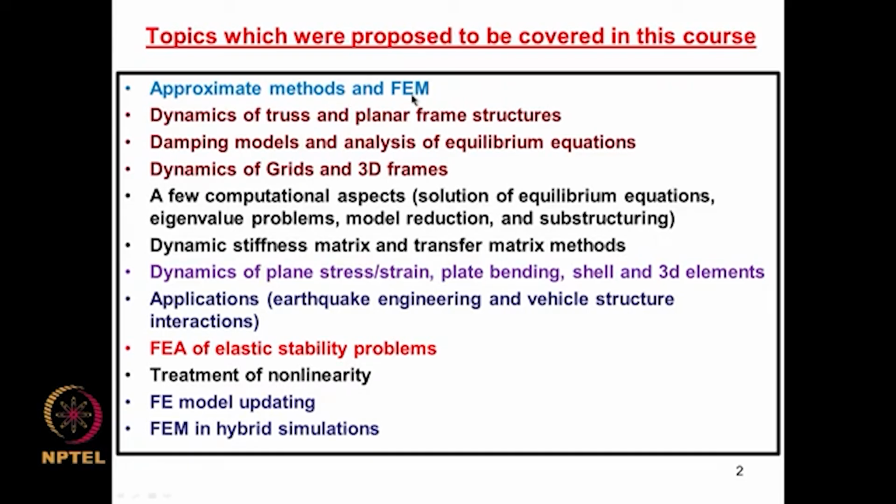The approximate methods and finite element method, dynamics of truss and planar frames, damping models and analysis of equilibrium equations, dynamics of grids and 3D frames, and some computational aspects like solution of equilibrium equations, eigenvalue problems, model reduction and substructuring. Then review of dynamic stiffness matrix and transfer matrix methods. Then dynamics of plane stress, plane strain, plate bending, shell and 3D elements. Then applications to earthquake engineering and vehicle structure interactions.